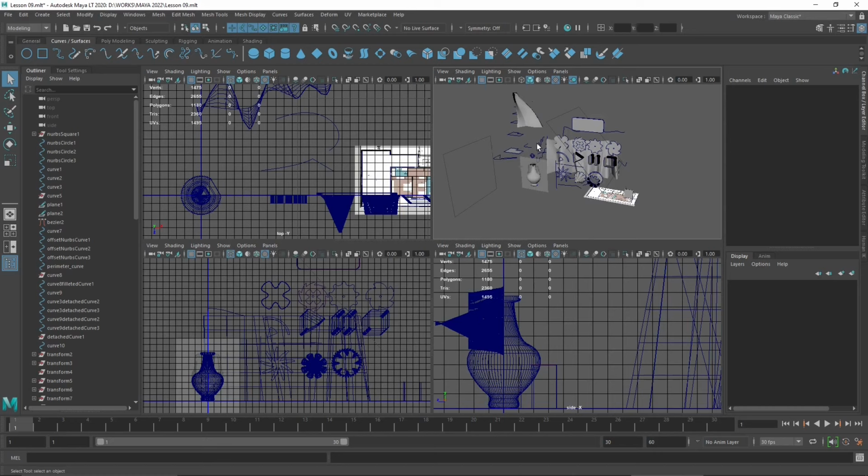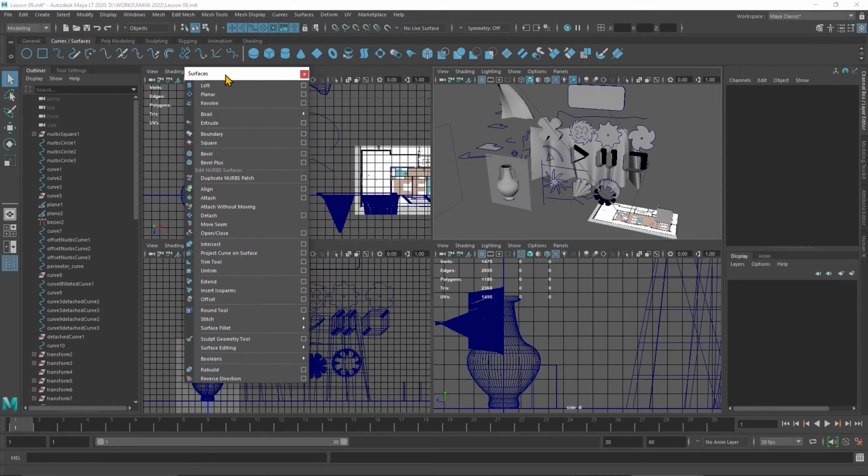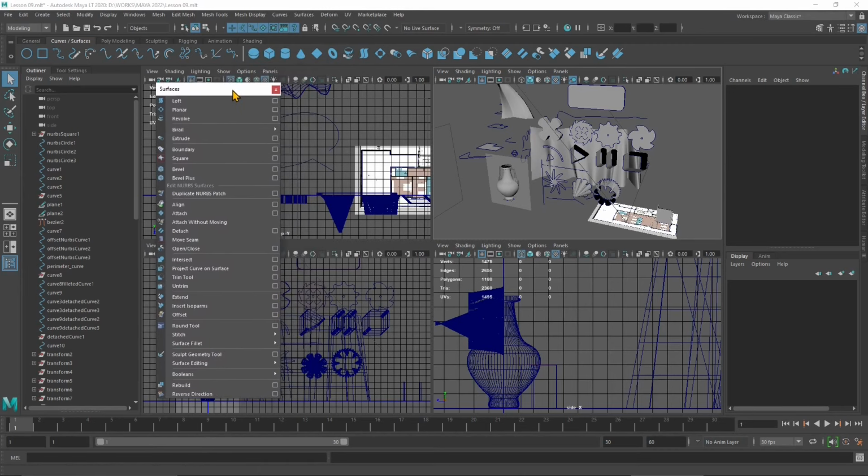Now the main difference is that when we create NURBS modeling objects, we usually start from 2D, from curves, and then from the curves we generate surfaces, and then we can generate also more complex surfaces and poly surfaces, which means assembly of surfaces, and then solids. So we usually start with curves and then we proceed with surfaces, as we saw also previously in other videos.